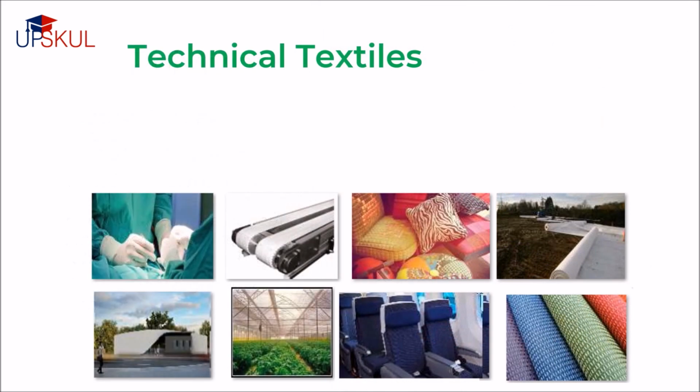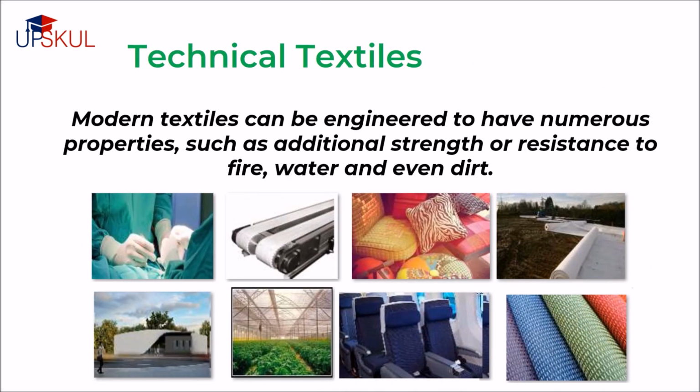The last subcategory of modern materials is technical textiles. Textiles have come a long way from the early days of cotton and silk, and today's modern textiles have some very advanced and useful properties. A major advancement in textiles technology was the invention of polyamide, more commonly known as nylon. This synthetic material can be pulled into very thin strands when heated and spun just like natural textiles, and is now used extensively as a fabric in clothing.